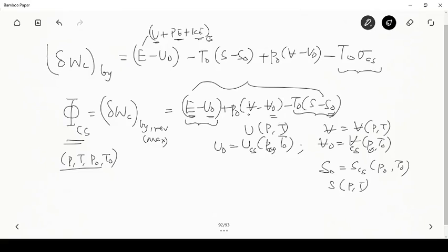So that part gets removed, and this P0 into V minus V0 is basically nothing but the displacement of the boundary from V to V0 against the dead state pressure P0. Okay. Whatever was done with respect to an excess of pressure over P0 was delivered as useful work, but P0 into V minus V0 is not constituting useful work. So that's the basic premise.